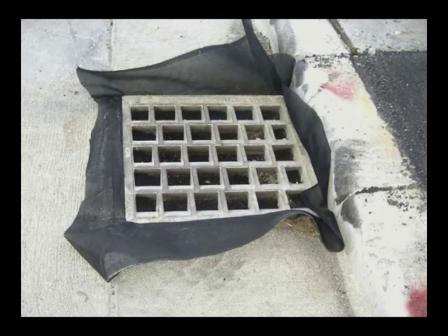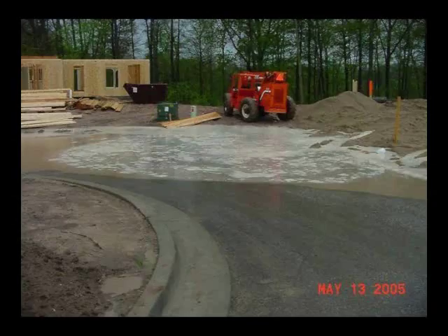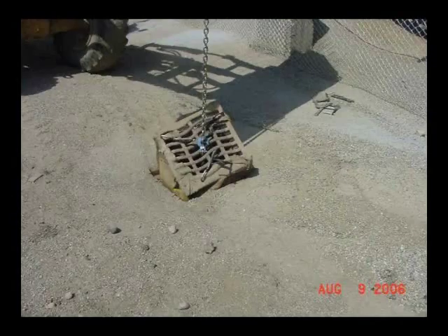It is never recommended to place flat filter fabric under a storm grate as inlet protection. Most rolled fabric materials are not suitable for the drainage needed in a drainage system. The fabric will easily clog and cause flooding. Removal is also difficult because there is nothing to prevent the soil and fabric from dropping into the manhole.